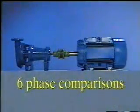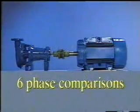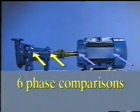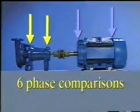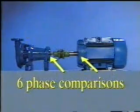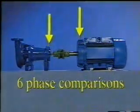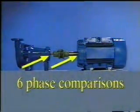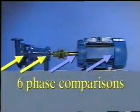There are 6 radial and 6 axial phase comparisons used in diagnosing machinery conditions. The radial comparisons are horizontal to horizontal for each component, vertical to vertical for each component, horizontal to horizontal across the coupling, and vertical to vertical across the coupling. The axial comparisons are from component to component across the coupling, end to end of each component, and side to side for each component.